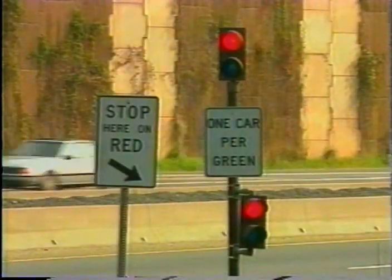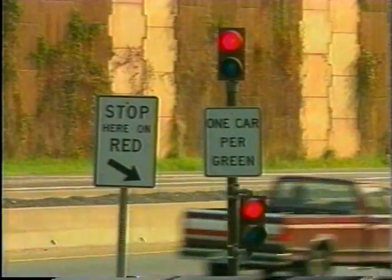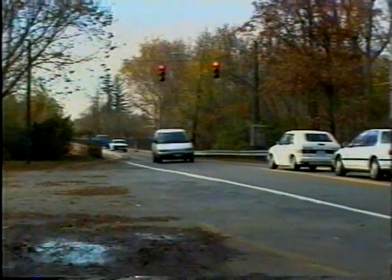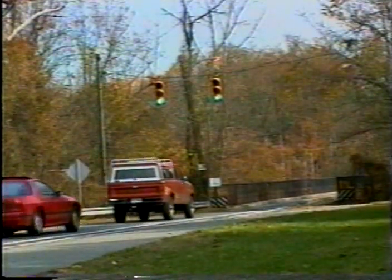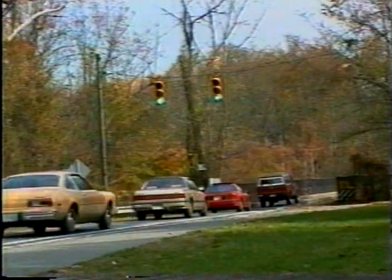Freeway ramp control signals. Standard traffic control signals installed at the entrance to freeway on-ramps. They are either 2 or 3 lens signals with red and green or red, yellow, and green lenses. Narrow bridge or tunnel signals. Also standard traffic control signals. Their purpose is to control traffic through a narrow roadway section where two-way traffic would be unsafe.